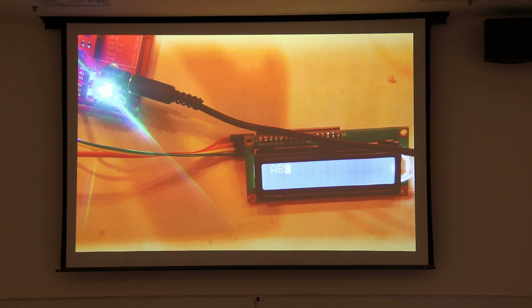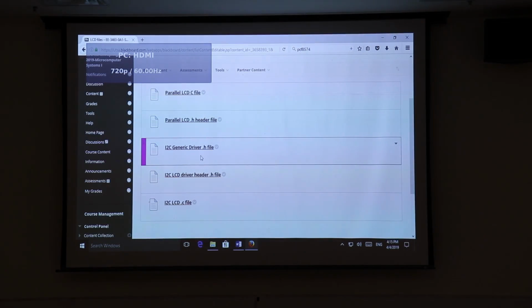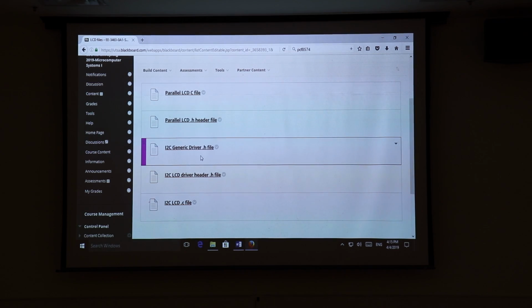Okay, so in this case, almost all the ones we have, if you buy them commercially and you just solder them into your 2-line by 16 LCD display, they'll either read hex 20 or hex 27, and usually nothing in between. But you can usually set them for anything in between that you want. But they usually come out of the factory set one way or the other. All those address lines are either tied high, and then you have to pull them low, or they're tied low and you have to tie them high if you want. And they usually have little solder pads for you to do that, but not always.